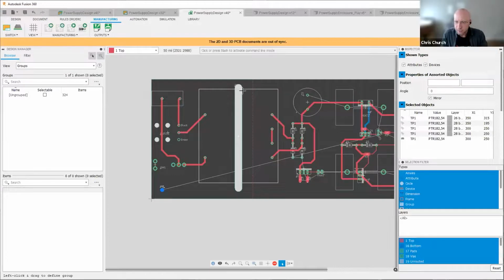And I see another question here. I think Andy asks, what's the best way to capture panel tooling holes, whether it's Rabbit, V-Score with MacroFab, and do we have any suggested templates? With the MacroFab platform, it actually automatically does the panelization. We prefer not to take panelized designs because the panelization changes depending on the lead time, which factories it may go to. We match the order to a number of factories and a number of different vendors, and we optimize the price and lead time around that.